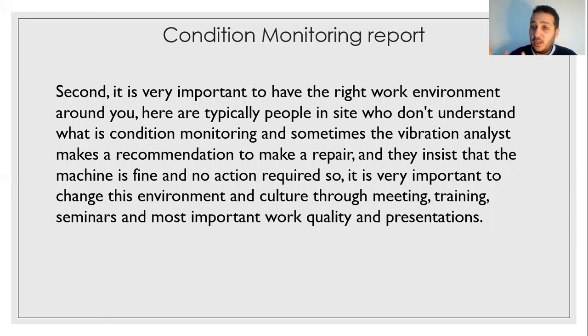Show them what you did, show them what you found on the vibration spectrum and what you found on the bearing. Show them that you had high vibration because of imbalance, and when you asked for balancing and did the balancing job right, the vibration dropped. Show them your work, show them what you're doing.